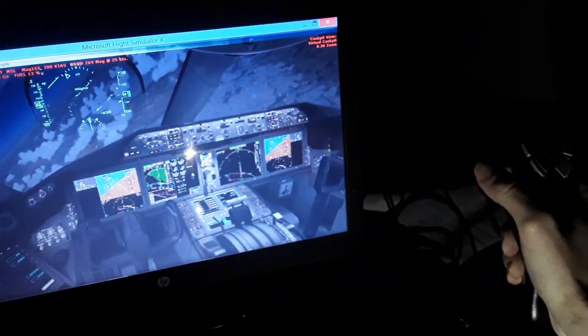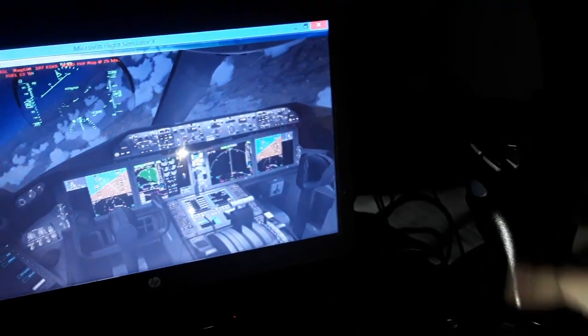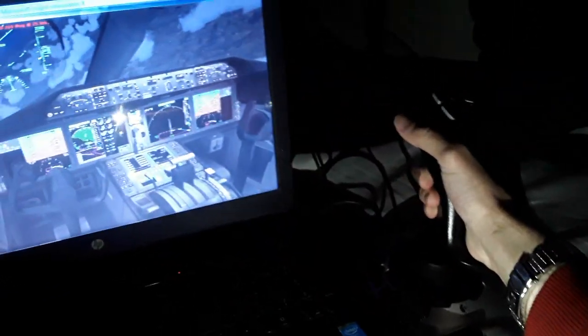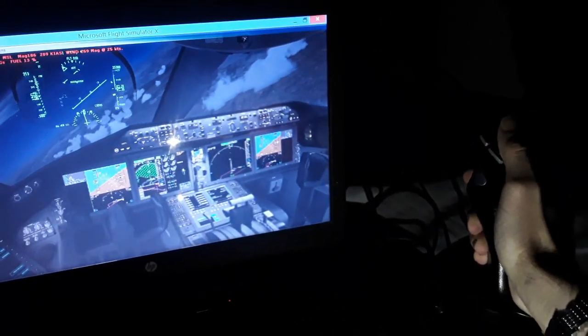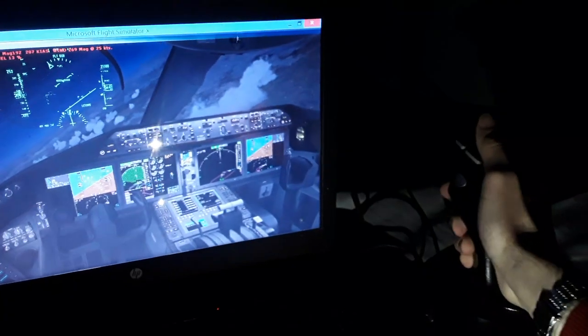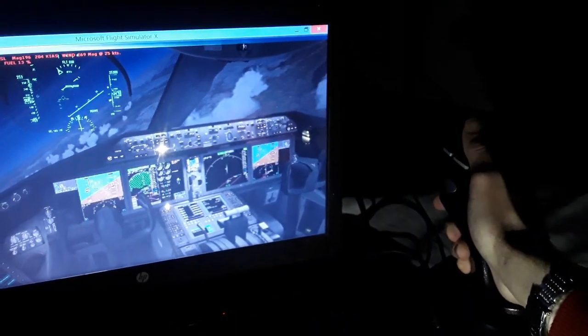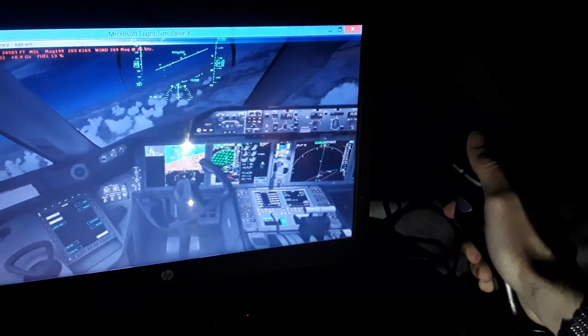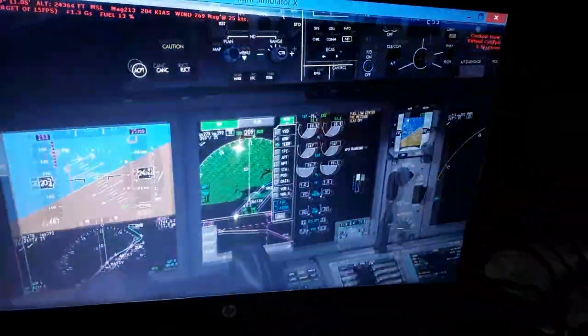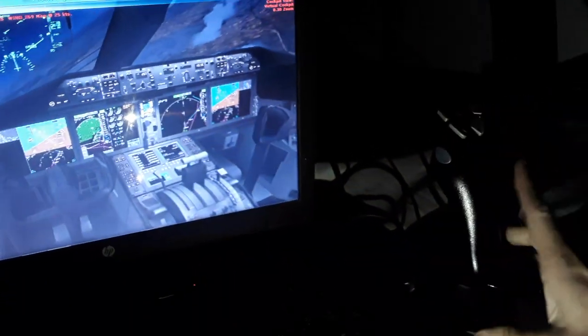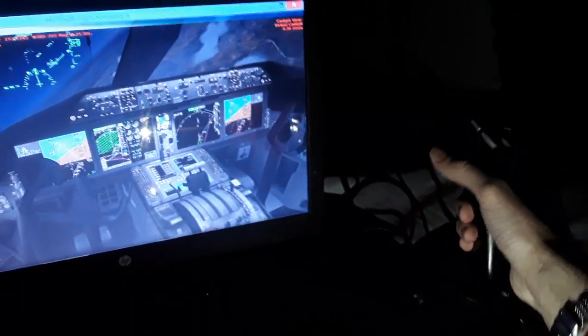Use also some right rudder for this turn to make it more, and decrease a little bit the thrust levers, so we'll turn more sharply with less thrust from the engines, like we're skidding more easily in the turn. So you can see we follow again these lines, the flight line, and we need to keep climbing, advance the thrust levers again.